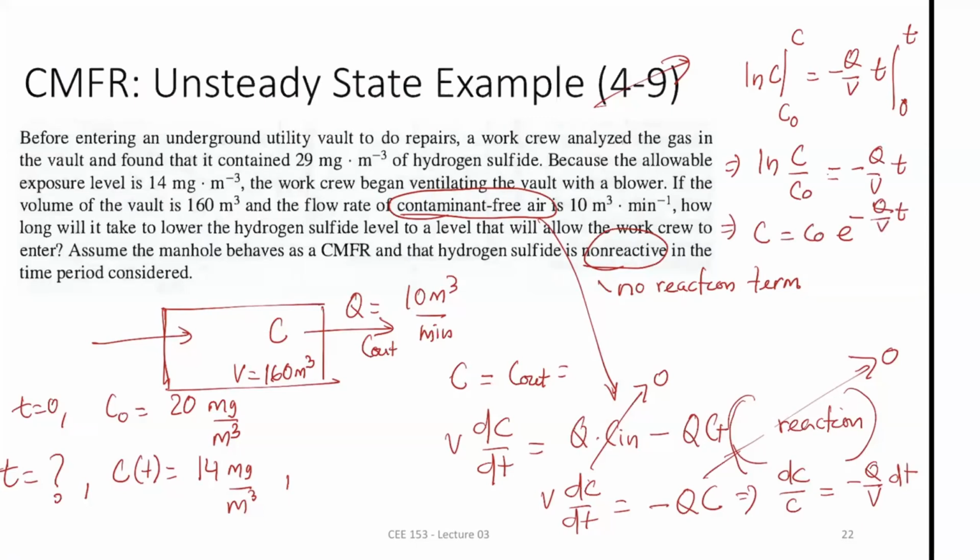Okay. So now you know the C0, that's given 20 milligram per liter. You know the Q, that's given 20 meter cube per minute. Volume is given in meter cube, and time is then a reaction. Time is given how much? How long? Oh, you are actually calculating time. I'm sorry. So let's not bring it here because that's easier to solve here. Okay, because you are asked to calculate time. So time would be minus volume by Q if you take the other side, ln C by C0.